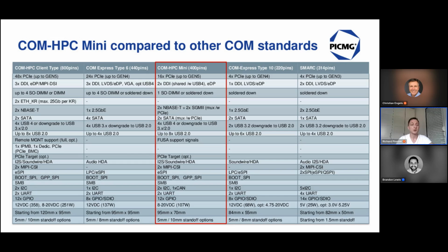A lot of applications require camera connection, so we added FFC connectors on the PCB. So MIPI CSI support in this regard has been predefined. This helps to keep the camera cabling consistent across CPU generations and different vendors. So we have a straightforward SPI, eSPI, and SMB bus on the module. And first time we put CAN on the module. That's great. So it has been added and it allows one to enjoy, for instance, embedded CAN controllers of silicon.